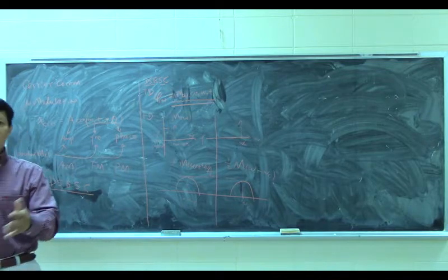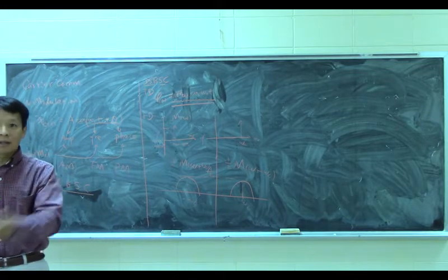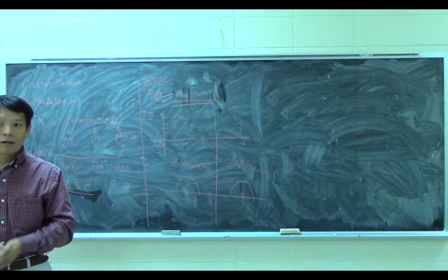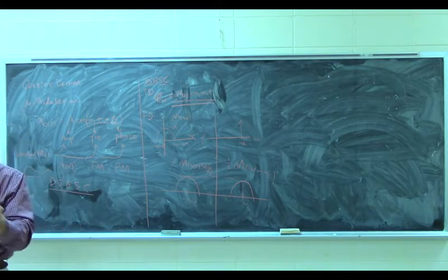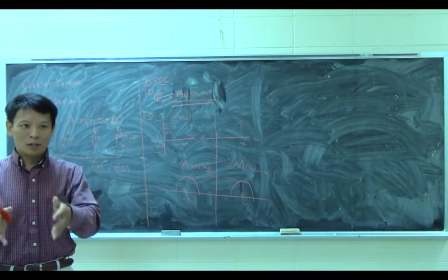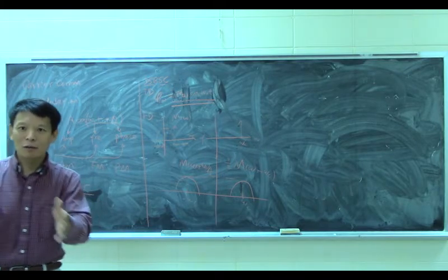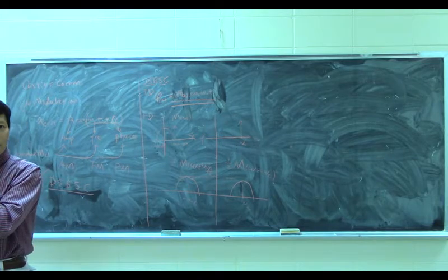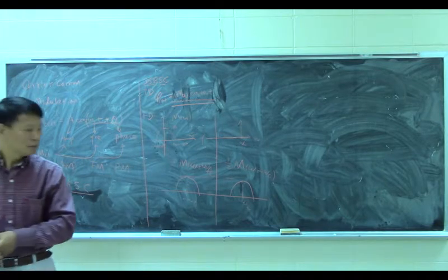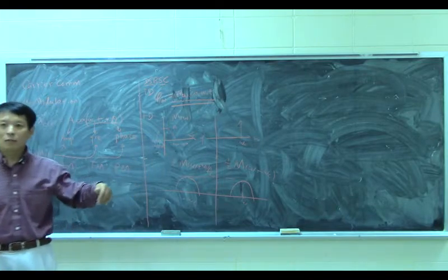Shifting: you shift your frequency to a higher frequency, that's all. Our voice is from 0 to 20K. Now, if you listen to 950K, you shift your voice from 0 to 20K all the way to be centered at 950K. So, very simple, right?